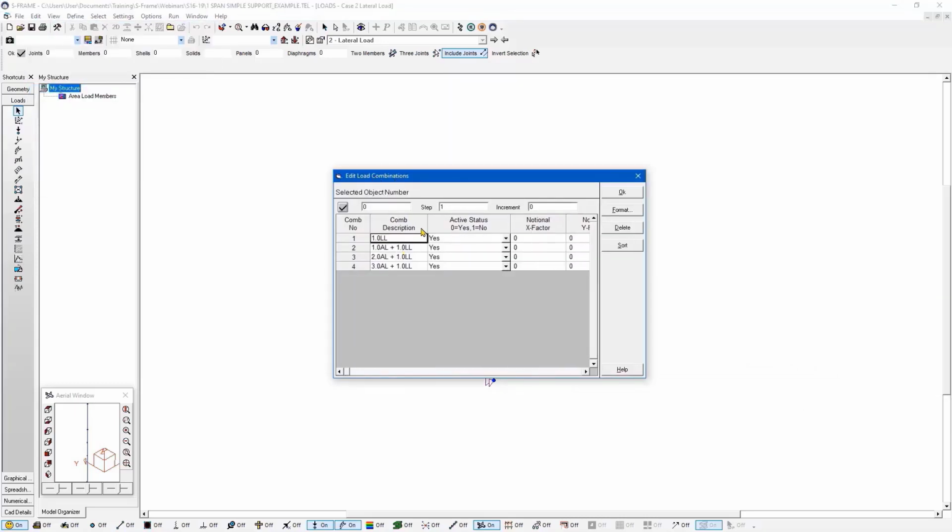Actually, sorry, I have multiple load combinations, but the same behavior in general. So we have one that just contains our lateral loads, one that contains the axial loads plus the lateral loads, one that contains an increased amount of axial load plus lateral load, and so on. You get the idea. We're just gradually increasing the amount of axial load while maintaining the same lateral load in each scenario.